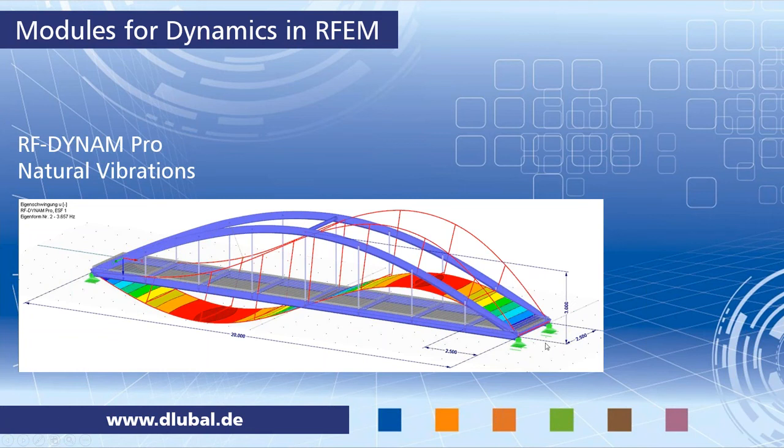which you can use to analyze frequencies and mode shapes for member surfaces and solid models. You can directly import the masses from load cases. You can combine these mass cases in mass combinations. You can also import stiffness modifications, so for example, to consider the pre-stress of cables, or you can deactivate some members. You could consider the stiffness from RF concrete, and so on. So this is considered as initial conditions.